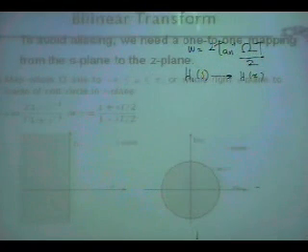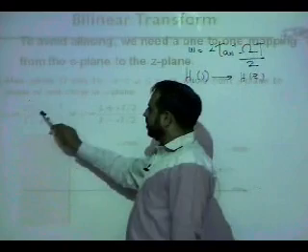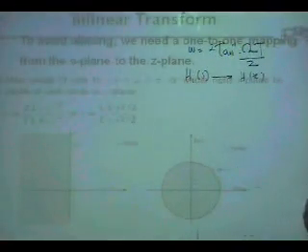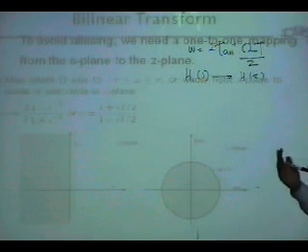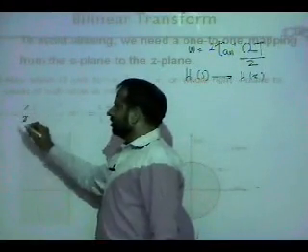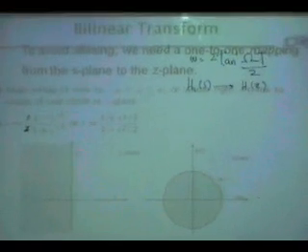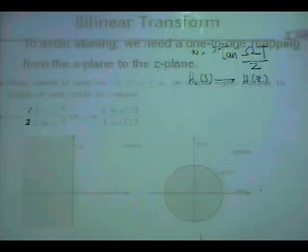It is this translation which says replace every s by 2 by capital T, 1 minus z inverse over 1 plus z inverse. So wherever you see an s, let's take a general case. In a general case, you can always take T equal to 2 so that you just get rid of this, but remember the 2 means that while you are translating the specs and then while you are translating the design back, in both cases it should be 2.